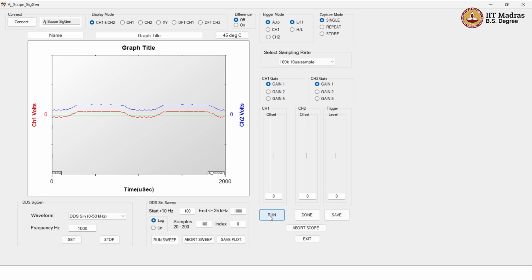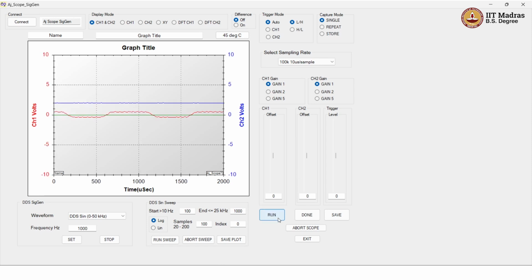So those of you who have the hardware with you and have got the software also, right now you can use 2 USB ports from your laptop itself to power. Nothing will happen. Okay, we are confident the fuse blows. In fact, the fuse blows sometimes. It's a fuse which we have optimized to be on the lower side. So sometimes, even when you're doing something useful, you might blow the fuse, which is better than not blowing the fuse when something dangerous happens, right?